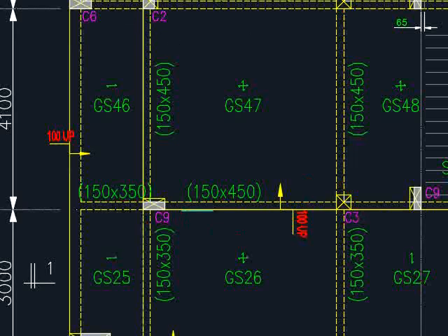But when you see the solid line here, that means the edge is visible from the plan, and the drop will happen here. This will be 100 mm higher, and this will be 100 mm lower. The edge will be here. It is basically on the basis of the geometrical drawing. For the things that you cannot see, it will be the hidden line. For the things that you can see, that will be the solid line.